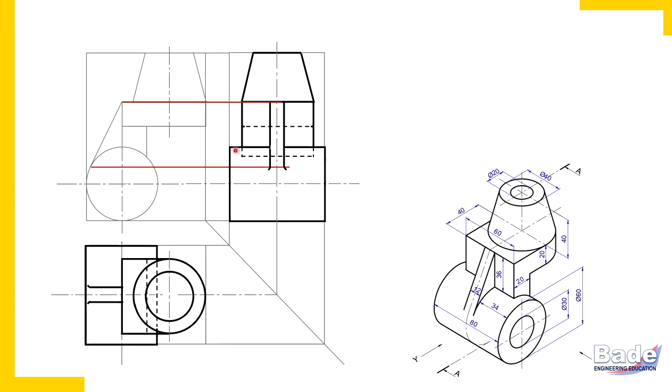Then on boundary generator of a cylinder, when there is an attachment, this boundary inside the attachment to be erased. So I have erased it. So trim that portion. Okay. So this plate is also over in the side view.